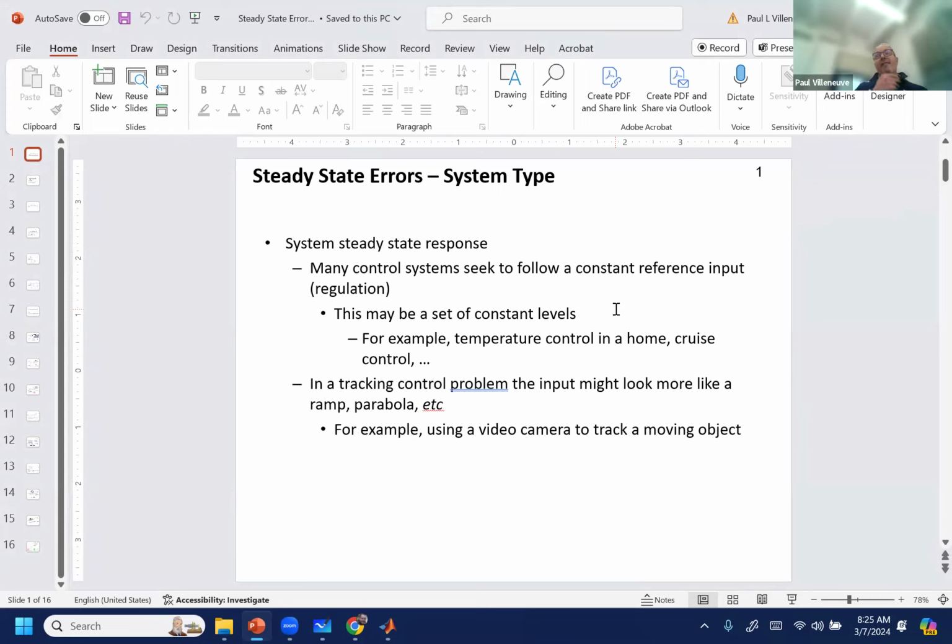Yeah, like I said, I've been doing this a little bit through the semester, and even last semester, when I was introducing poles and zeros, and I said, hey, when we look forward, you have to have the same number of poles and zeros. And I have a mantra, if anybody knows what a mantra is, you say it over and over again, it kind of gets burned in your brain. So for doing root locus, I always say start at a pole, end at a zero, start at a pole, end at a zero. And if you say that enough, it starts to help you understand how to lay these out. And so last semester, I think I did say it once, start at a pole, end at a zero. That's a precursor for what we'll be looking for this semester, but we won't go too crazy.